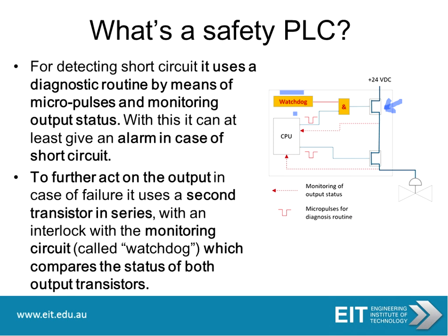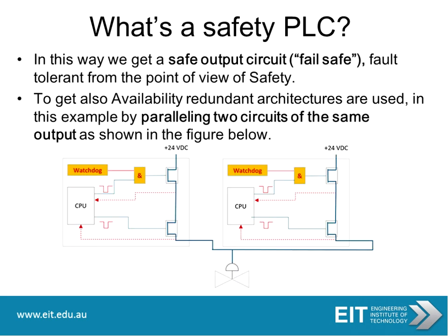So there's your indicator of your micropulses, and there's, in dotted lines, the monitoring of the output status of both of these switches. So in this way we get a safe output circuit, fail-safe, fault-tolerant from the point of view of safety.